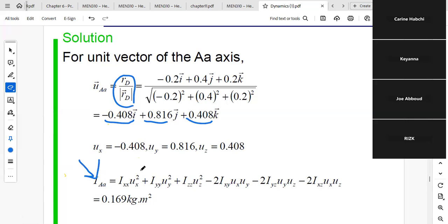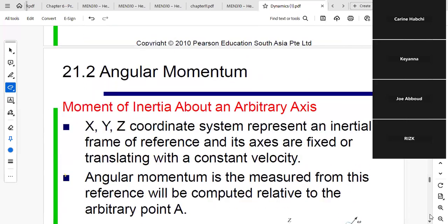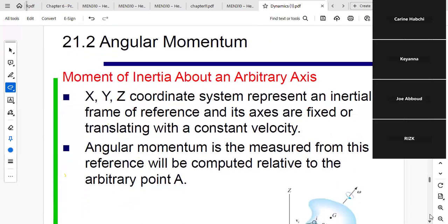So now if I tell you you have rotation about this axis, pure rotation, 2D motion, then you can use this inertia and say that the sum of moments about this axis is I times alpha vector. Okay. Any question on this? Okay. Now, what about the angular momentum? So we know from previous analysis that the angular momentum is...